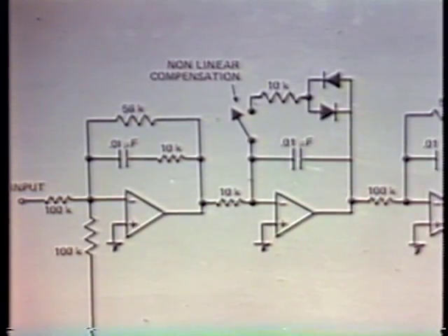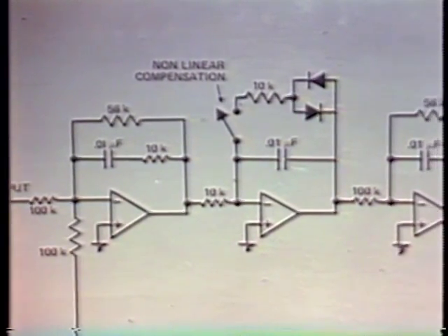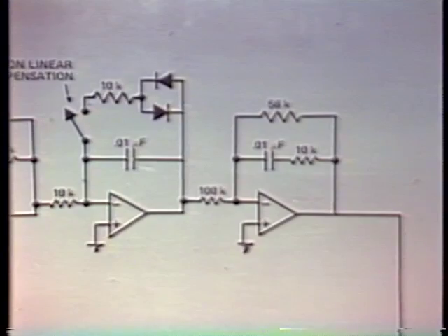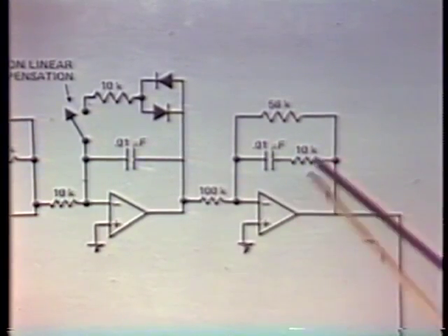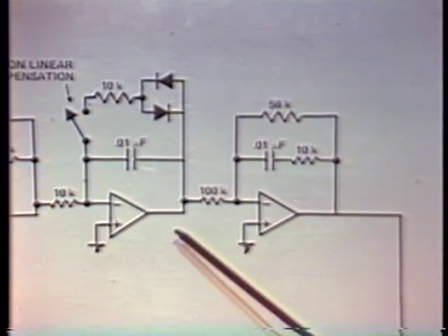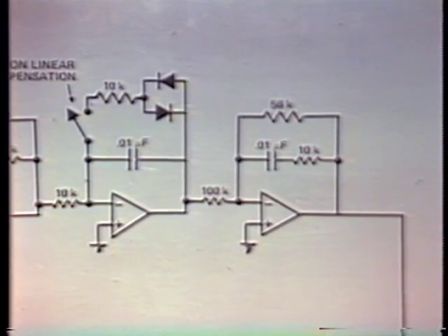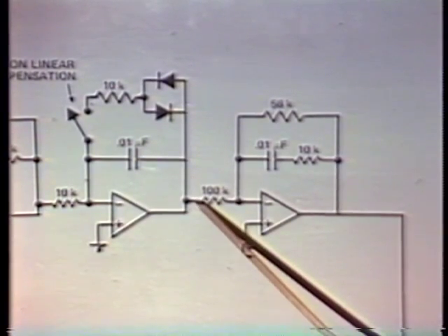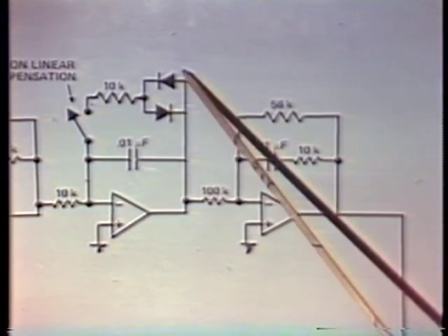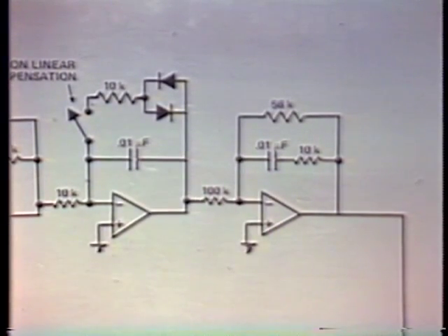If you keep track of the maximum signal at this point, we found out that that's about 6 volts. If you go back through the gains of these elements, you find out that as long as the system's in its linear region, the signal level at this point is quite small. It's less than a diode drop, less than the forward drop of a diode.